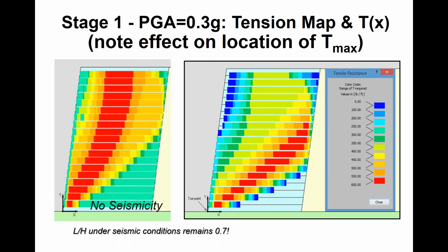And you can see that here. Here that band exits at the toe, as you might expect, and goes directly to the midpoint of the wall where it exits into the retained soil. So in this case, we're actually capturing the reinforcement demand of a compound mechanism, of failure surfaces that pass through both retained and reinforced soil. So here we're able to capture the demand, not just for internal stability, but compound.